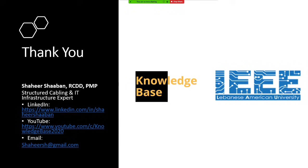It is an option, and you can see some data centers now have their roof fully filled with solar panels. However, from my experience, I have not seen it as a main power supply for a data center. The reason is that in a data center, you always need 100% reliability. As we mentioned, you need 99.99 availability in the data center. So it's used as a secondary power supply. I haven't seen it as a main power supply till now.